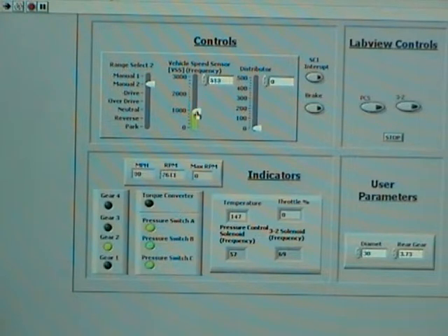So we can see that here in gear 2 you shift between gear 1 and gear 2, and that is all that is allowed. And there's a set mile per hour that it's going to upshift to gear 2 to make sure that there's no damage done, which happens around, I think, somewhere between 35 and 45. Here we're seeing it at relatively 35 or 37 miles per hour. And then manual 1, as you would probably assume, it will keep the shift solenoids locked into 1 so that the shift solenoids logic is keeping up with what the transmission does mechanically anyway.